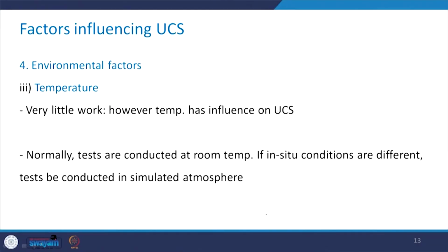Now, the effect of the temperature, although very little work has been done, however, whatever work has been done shows that the temperature has significant influence on UCS. So, normally the tests are conducted at room temperature, but if the in situ conditions are different, then tests should be conducted in the simulated atmosphere.